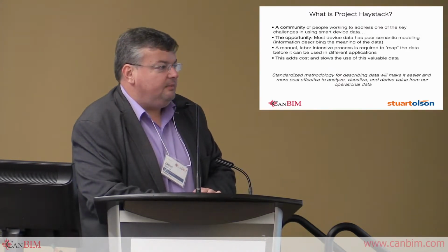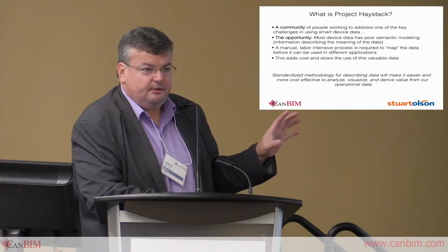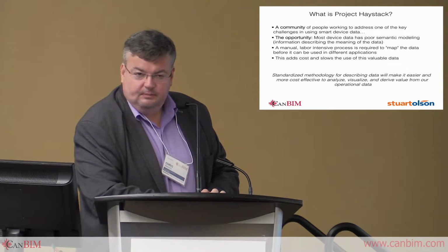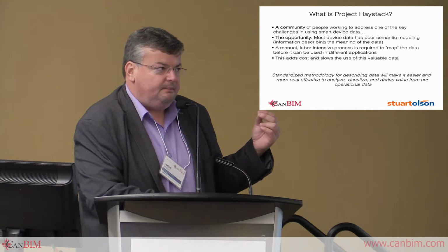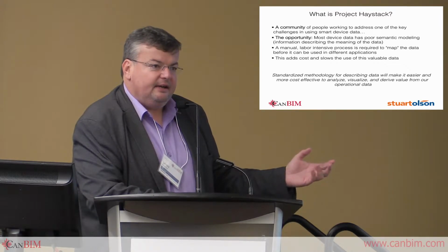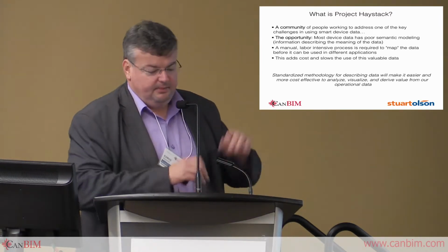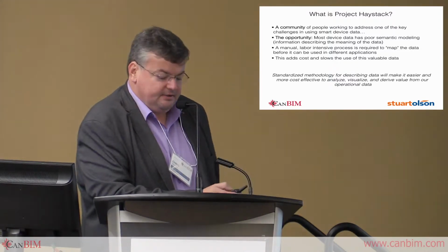They are now trying to deal with exactly the same problem that we're having on the buildings control side, not too dissimilar from what's happening on the BIM side. What we want to look for is when we're doing building controls, they are not just temperature controls in a room, but also things like lighting control, temperature, heating settings, setbacks, energy management, metering, all tied together. How do we control and manage this data? So we've decided to standardize on the Haystack approach because of dealing with different naming complexities and challenges that we see in the industry.